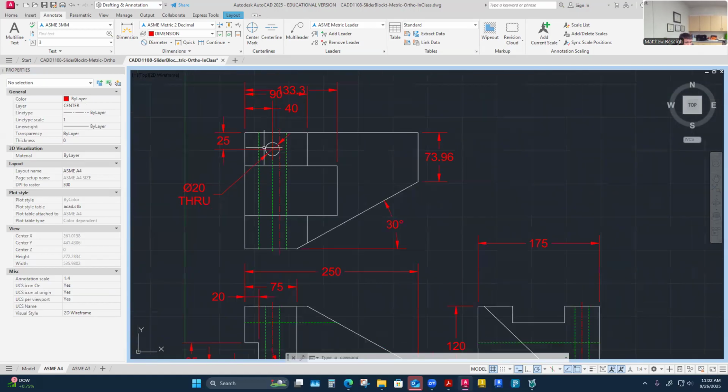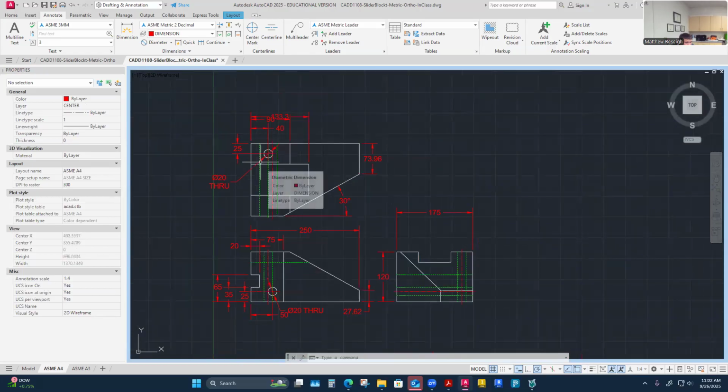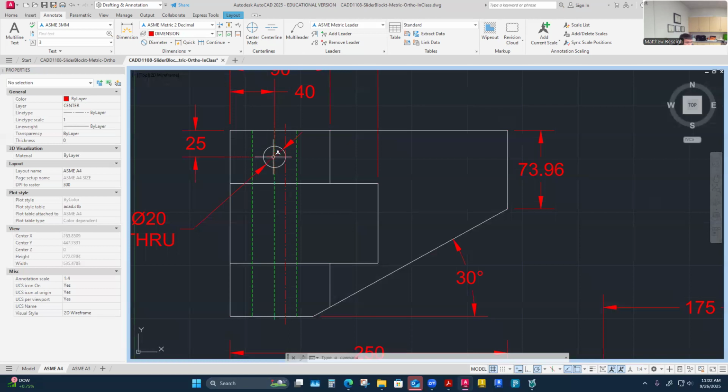Hole size and location has been kept good. These are really quite long. This is 120 millimeters of hole down through that. That's pretty long. And so in the future I may have to control how straight the axis of that hole is from the top surface to the bottom surface.